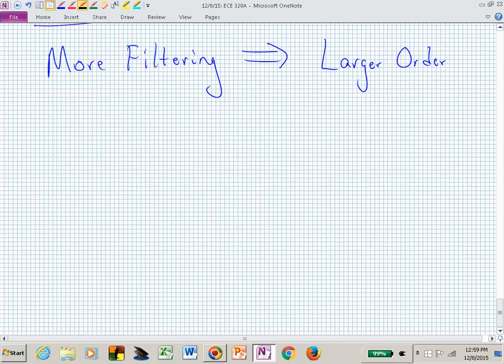Whew. Question? Kind of like on a side note, is omega in radians per second? The question was, is omega in radians or hertz? Radians per second or cycles per second, hertz. I will try to make omegas always in radians per second, and f's will be in hertz, so that omega is 2 pi f. If I talk about hertz, then you need to change that to omegas to do this scaling. And we'll try to do that with some of these examples, if I ever get there.